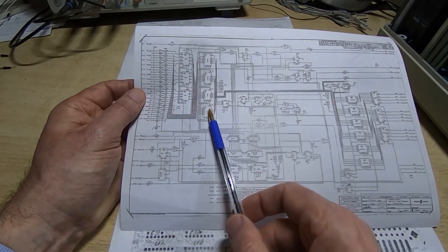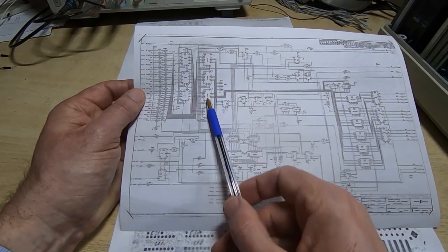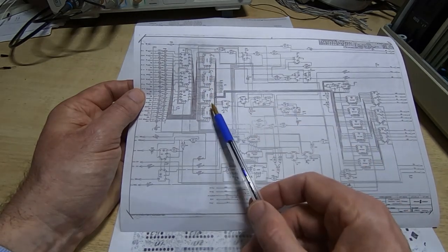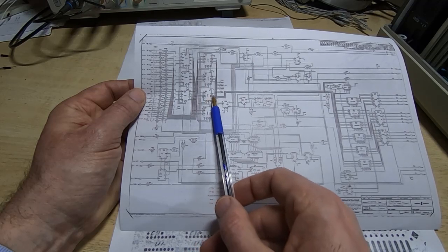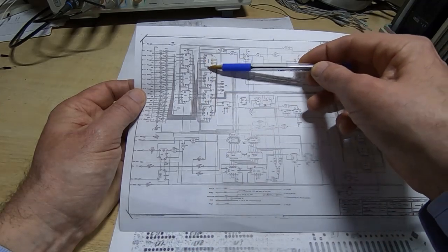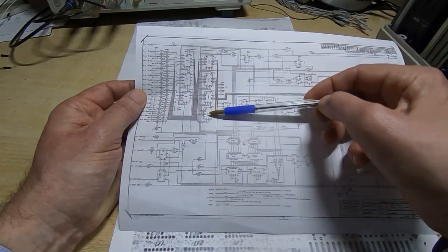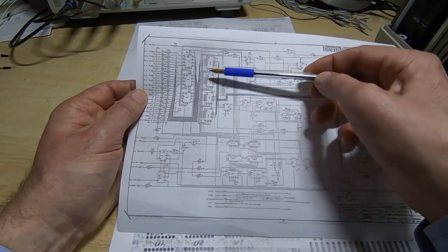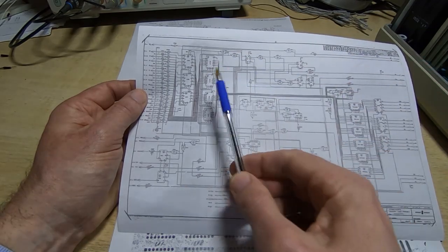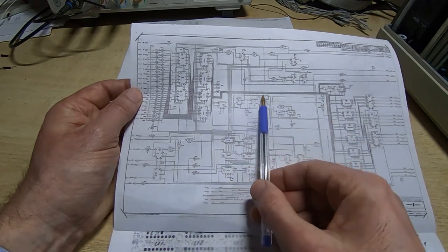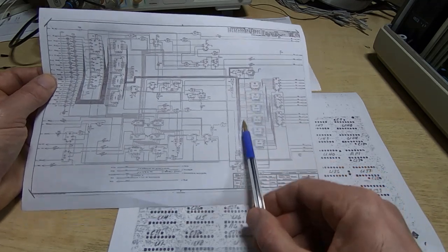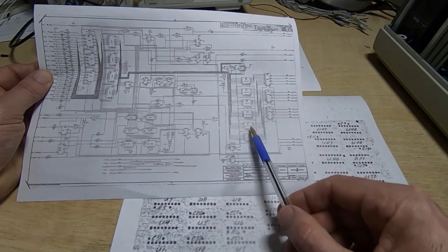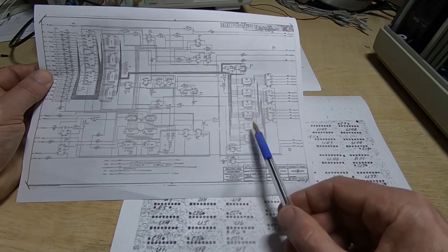They come in, they are latched using these 4 latches. It's latched as 2 8-bit values. It's basically selected as one of 2 pairs, so it's either this 8 bits or this 8 bits, and these are tri-state buffers. That 8-bit value is then fed along to this part of the circuit, and this comprises 2 80-byte or 80-character shift registers.